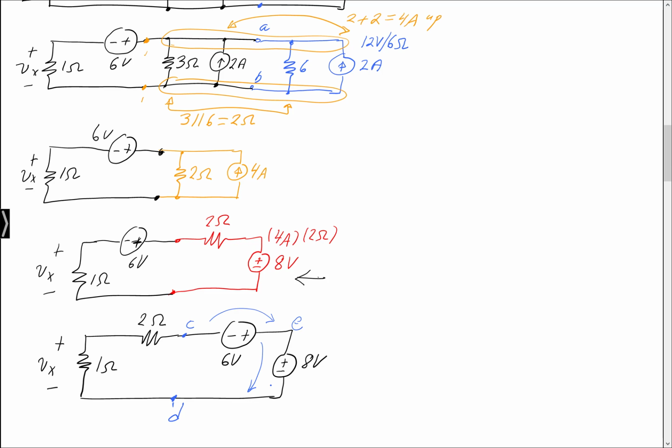Does that make sense? So then the net effect of going from C to D, you go up by 6, down by 8, is to go down by 2, right? So in effect, the voltage from here to here, from C to D, is actually 2 volts, right? Does that make sense? Well, how do we check it?